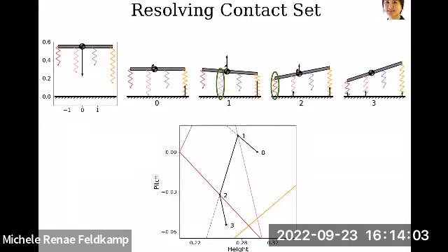So I just drop the robot down on the ground until one leg contacts. So once that one leg contacts, I can solve the equations and it projects a solution here. But it turns out that if I try to move to that solution, I'm going to hit a line, which is another leg is going to hit the ground. Well, the motion from here to here is a simple projection operation on this plane. Now I can do the same here. I calculate the solution here, and it turns out it's out here.